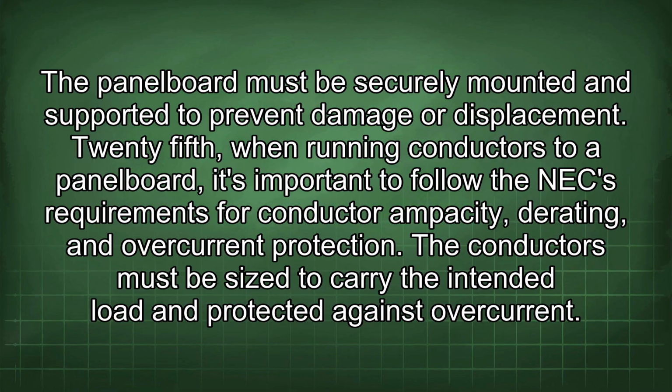25th, when running conductors to a panel board, it's important to follow the NEC requirements for conductor ampacity, derating, and overcurrent protection. The conductors must be sized to carry the intended load and protected against overcurrent.